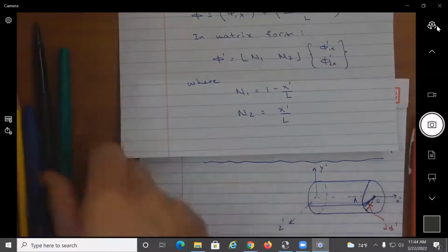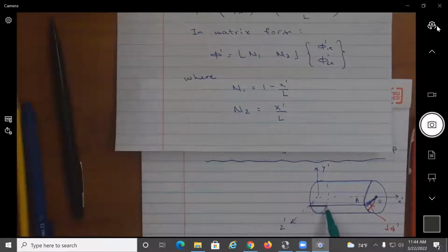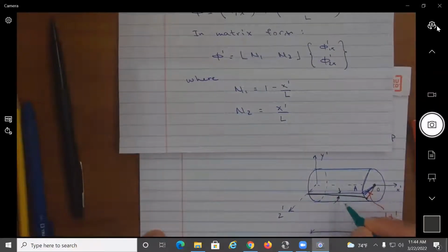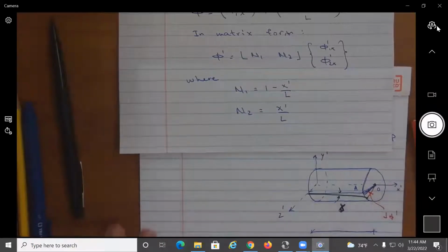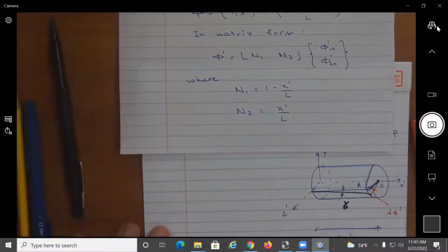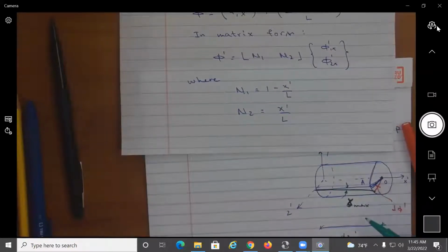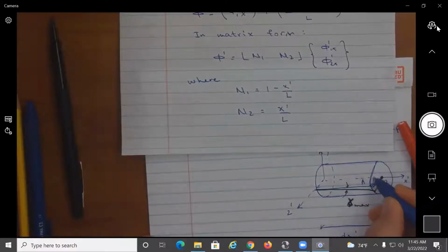And at the same time, this blue line will be curved like this. And this angle between the blue and the green will be gamma all the way through the length. This is how we measure the shear strain. I'm going to call this gamma max, because I'm going all the way to the outside where I have the maximum angle. So I'm using the entire radius. So this blue line has a length r.